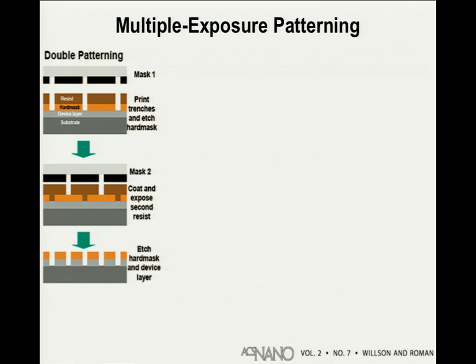The reason we can't do it is because the edges of this film have been exposed by diffraction. And in order to use a different mask to get the features here and here with the same resist film, the resist film in the diffracted regions would have to forget that they've been exposed already. So these are sub-threshold exposures that need to be forgotten by the polymer film. And so far, there aren't really any good ways of doing that.